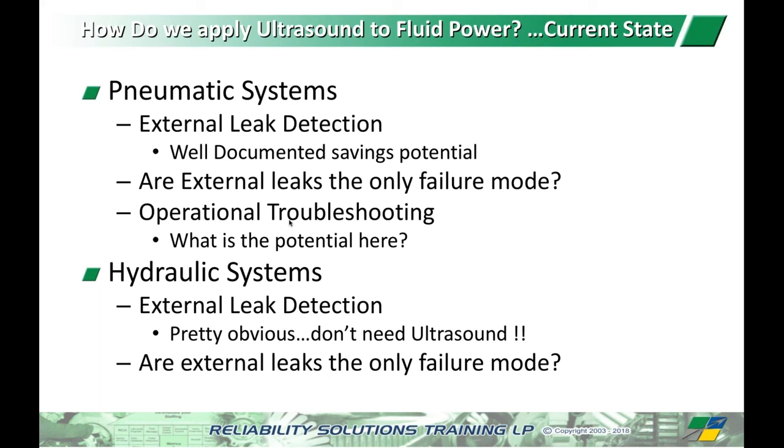We were then there doing some training for their operators, and started using an ultrasound gun to see if we could detect a problem. And when they had a problem with a unit, I got out there and was able to use the contact probe on each solenoid valve and just listen. And you'd go along the line and you'd hear, and you'd come back to it, and there was the one solenoid valve that was passing. So one 7/16 Allen screw later, a couple of O-rings, we replaced that one solenoid and they were back up and running.